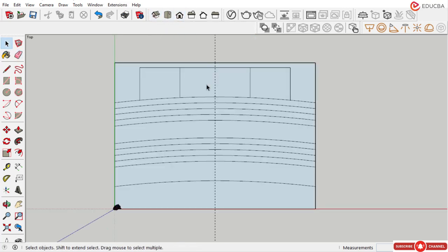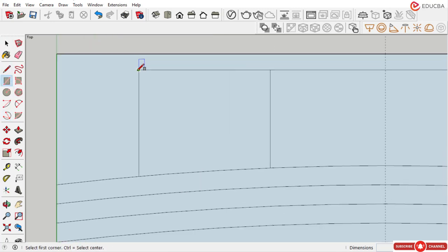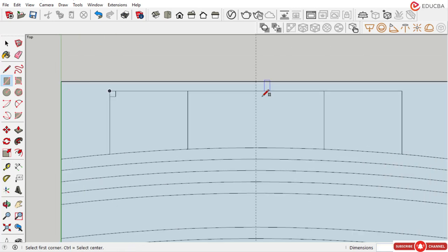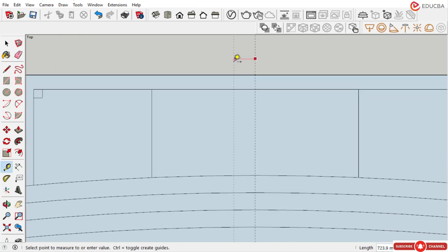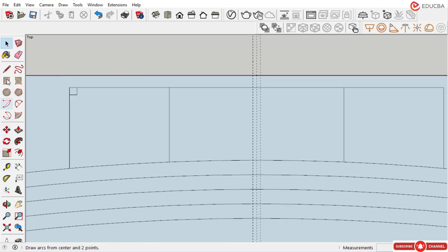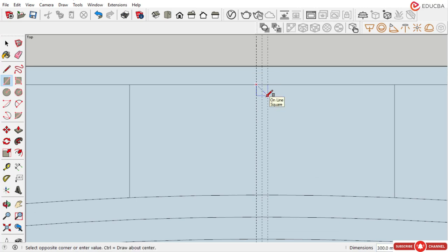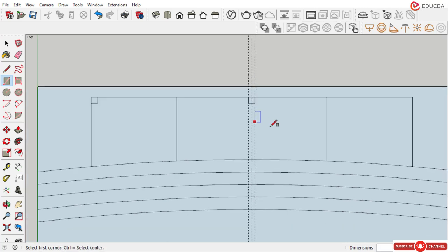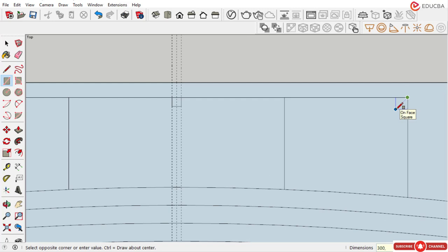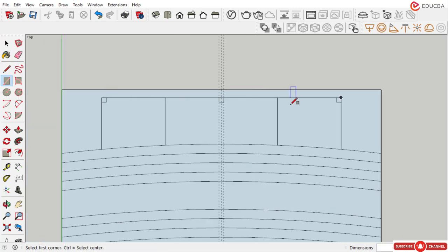Now for this shelter structure, we require a column for the cabin structure. So let's start the cabin design, and for that, rectangle from this point 300 by 300 mm. Again from here make 150 to here and 150 here. So again by rectangle from this point 300 by 300, and from here 300 by 300. So these are the three columns I have designed right now.